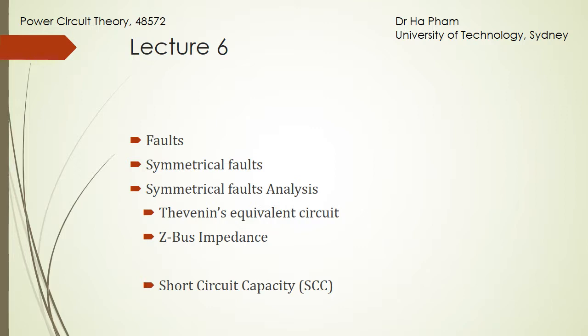Today we will discuss fault analysis, in particular symmetrical faults. We will discuss two methods. The first one is Thevenin's equivalent circuit and the second one is the focus, how to use the impedance matrix Z-bus to analyze a fault. And finally, we will discuss a new definition of short circuit capacity, or SSC.